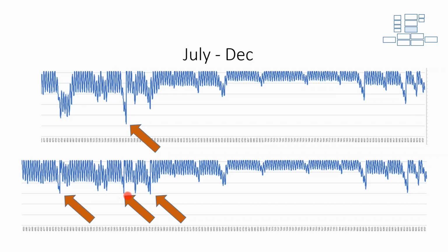We're going to click the generator on before we get to that point. So if we wanted to reduce the size of the battery bank from 122 kilowatt hours, could we have gotten away with an 80 kilowatt hour battery bank? Well, yes, but in that instance, we would be more reliant on the generator to actually work. And the client said, I'd rather spend more money and not rely on the generator.